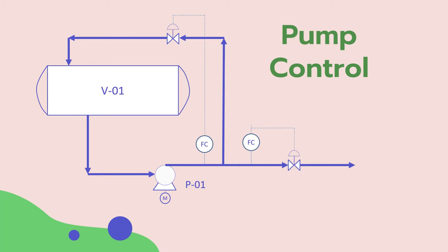Also, in order to prevent operating the pump at less than minimum flow, we would need to add a minimum flow control. This can have different forms as well. If you want to know more about pump calculations, performance curve and control schemes, you can check out the link in the description. Let's assume that we shall choose this control scheme.